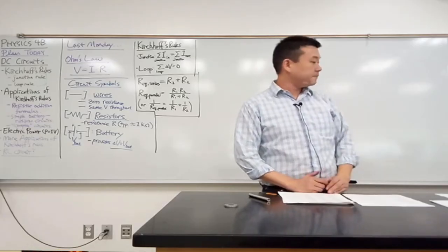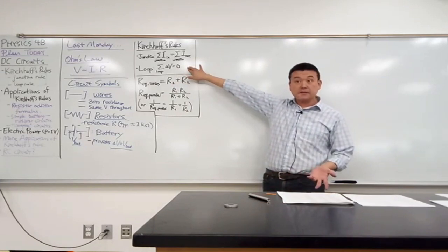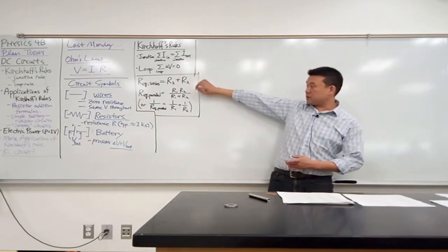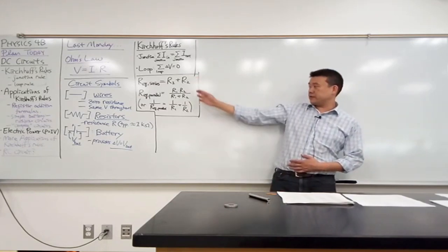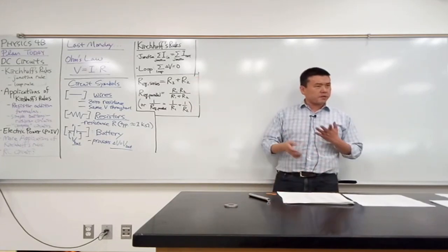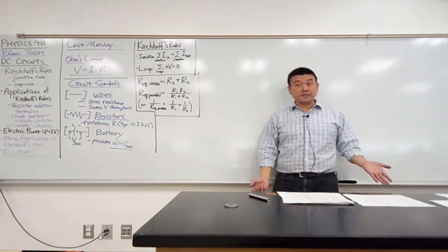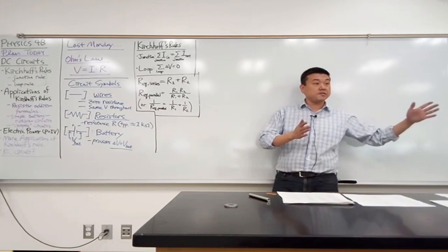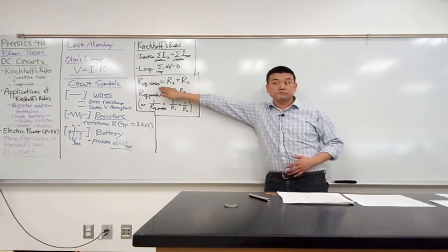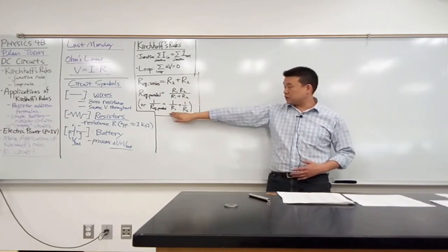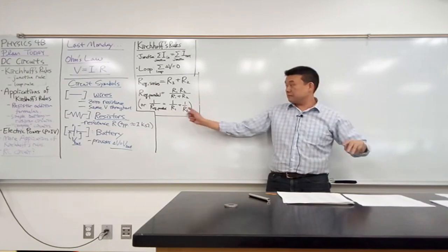So you guys saw the application of Kirchhoff's rules in very simple cases. And we even derived these formulas. And the truth is, there are a lot of problems you can solve with these. And I hope it's intuitive for everyone how you would extend this in case you're adding more than 2 resistors. Like if you're adding 3 resistors in series, what do you think the modified version of this formula will be? Adding them. Just one more, right? What about the modified version of this one if you're adding 3 resistors in parallel? Adding 1 over R3. And it's just here, right?